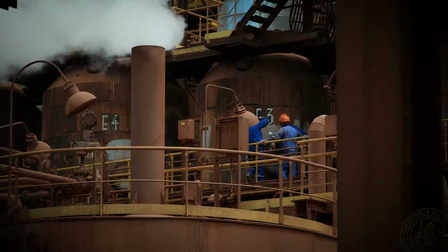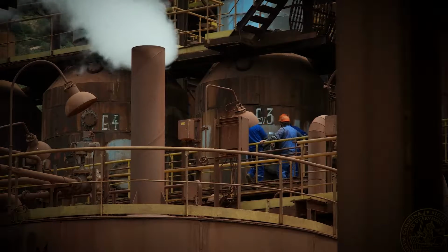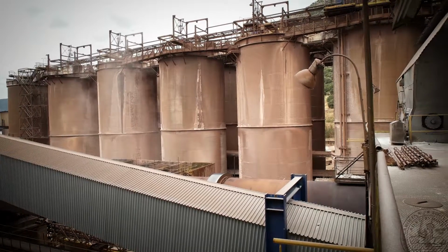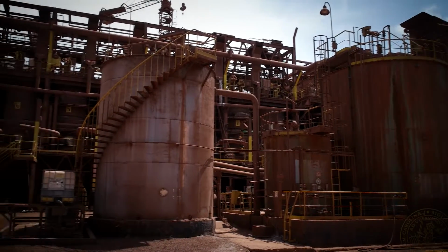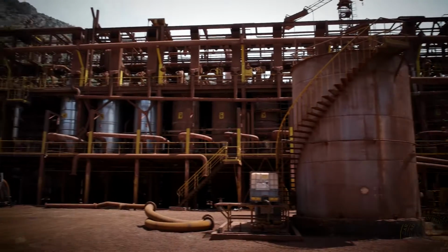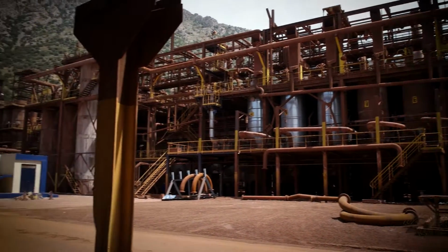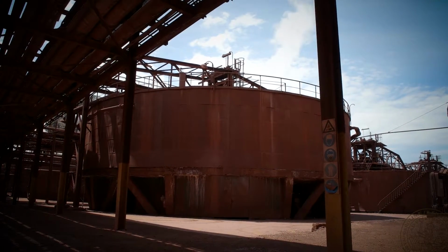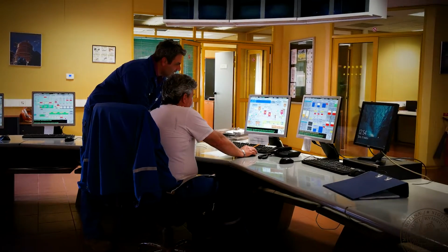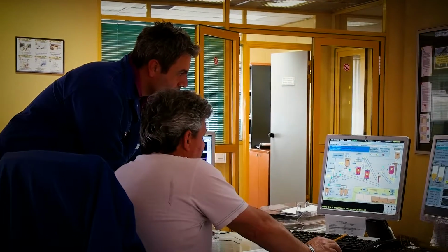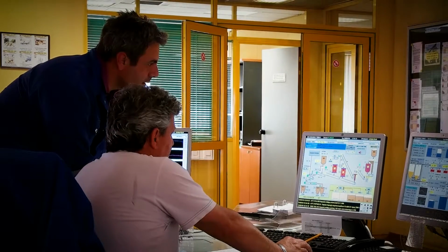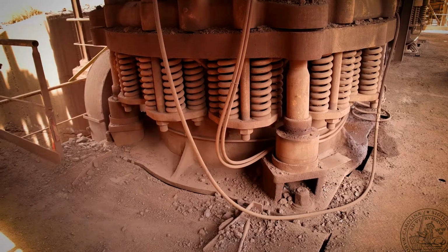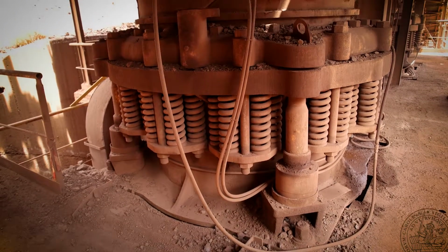And then after we have finished with the reaction, we need to cool down this slurry, and we use a series of flash tanks. We recover steam from these flash tanks and we cool down the slurry. This recovered steam is also used to preheat the slurry of bauxite coming into the digestion, so it is optimized thermally. At the end of the digestion, we have dissolved alumina in the caustic soda, and we also have some residues of bauxite, which is mostly iron oxide, as solids inside.